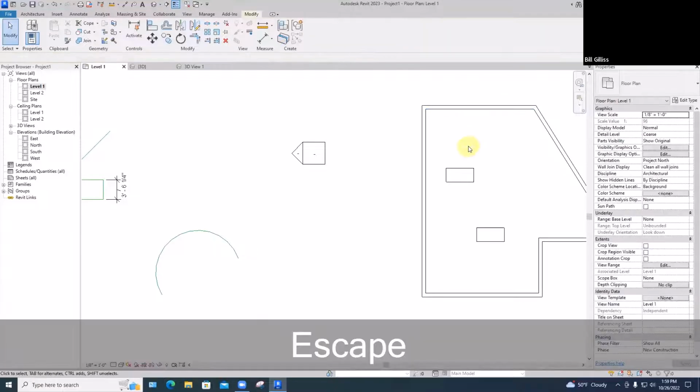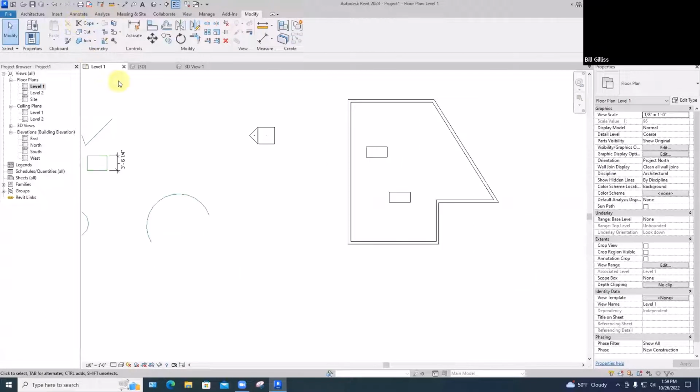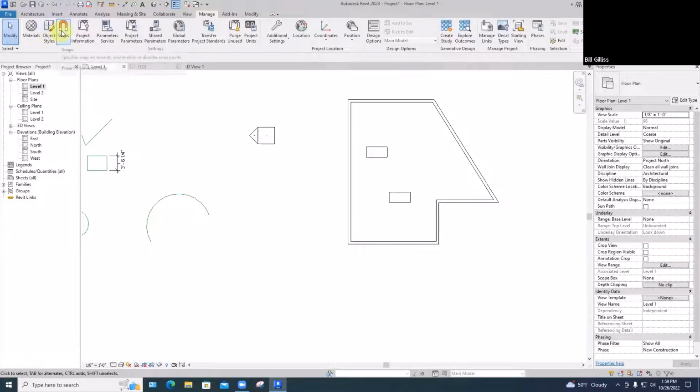We can change which cursor snaps Revit uses for its running cursor snaps. If you decide I just never want the centers of circles, those are confusing me, I don't want to show those. I think that's in Manage Snaps. Here we go.